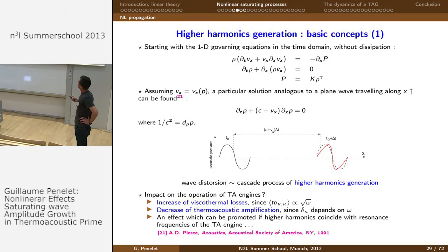Another reason is that a thermoacoustic engine is always designed for a particular frequency, which is that of the fundamental mode. So if we have higher modes, they do not participate to the thermoacoustic wave amplification. Moreover, this effect of higher harmonic generation can be promoted by the resonator itself if the resonance frequency coincides with that of higher harmonics.